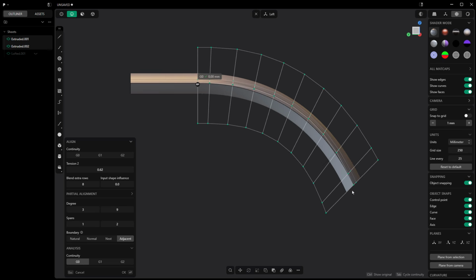And again, the degree is breaking up the curve into a specified number of sections or CVs, and the spans is adding multiple curves to the overall thing. And so when you add multiple curves, you end up getting more flat sections. They're not really flat, but you end up getting more flat sections because you're sort of localizing that curvature.